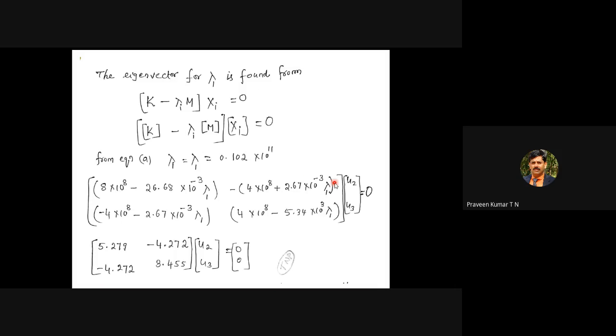Then U2 and U3 are not independent. U2 is not moved independently and U3 also is not moved independently. It is like your trains. To make it easy to understand, you have train bogies. Bogie 1 moves, and there is a relative motion between bogie 1 and bogie 2, because there is a flexible coupling between them. If bogie 1 and bogie 2 are joined by a rigid coupling, then there is no relative motion. But that is not possible; we require a flexible coupling itself.